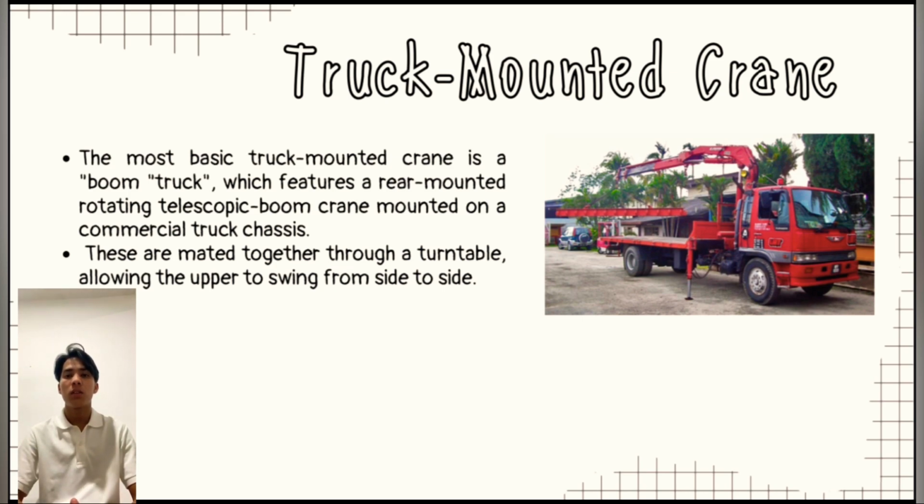These modern hydraulic truck cranes are usually single-engine machines, with the same engine powering the undercarriage and the crane. The upper is usually powered via the undercarriage. The crane is run through the turntable from the pump mounted on the lower. In older model designs of hydraulic truck cranes, there were two engines. One in the lower pulled the crane down the road and ran a hydraulic pump, fold-out outriggers and jacks. The one in the upper ran the upper through a hydraulic pump of its own. Many older operators favor the two-engine system due to the leaking seals in the turntable of newer design cranes.